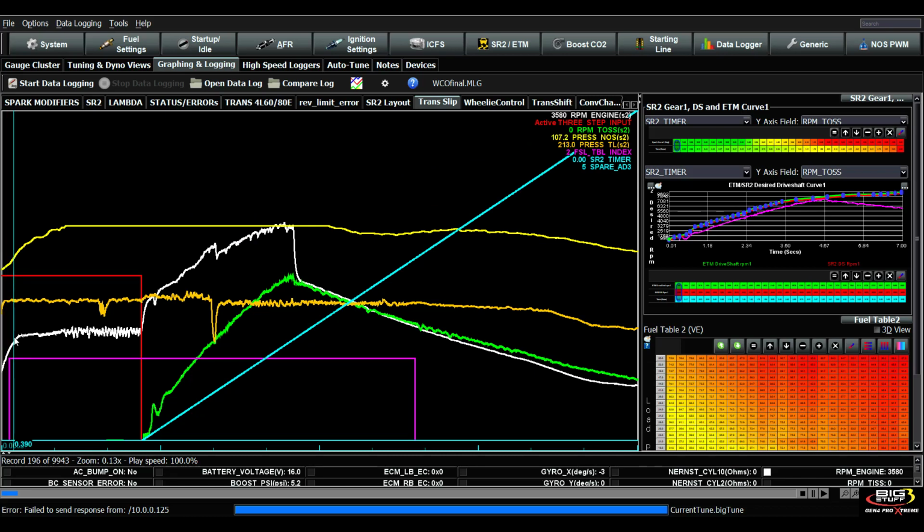So when this turns on right there, we turn on our second set of injectors. And you'll see that if I'm on FSL table index 1 up here in purple, and then as soon as I come up here to FSL table index 2, that's the exact point that we actually switch to the second map. That's how that works.